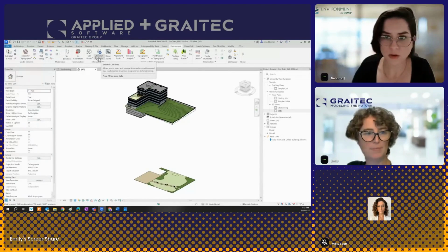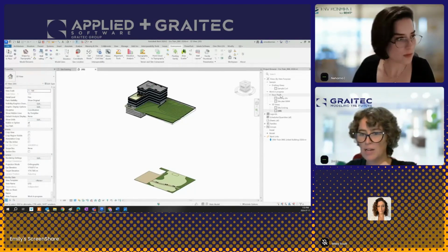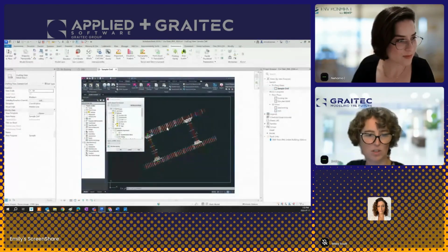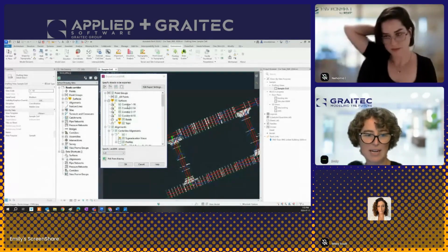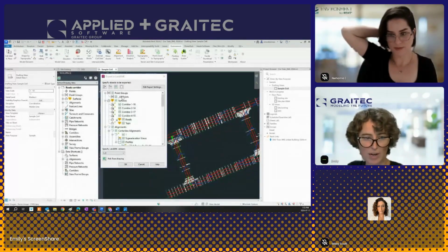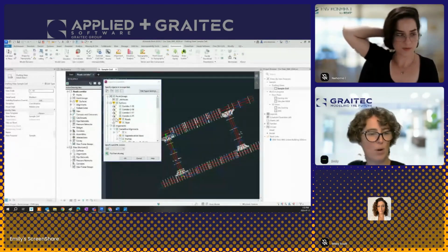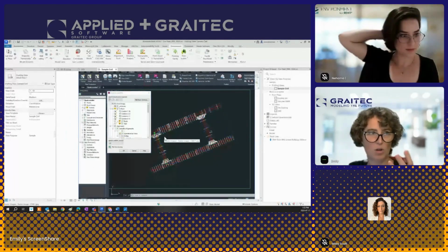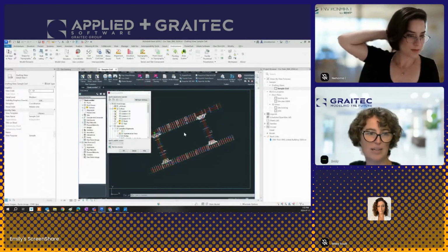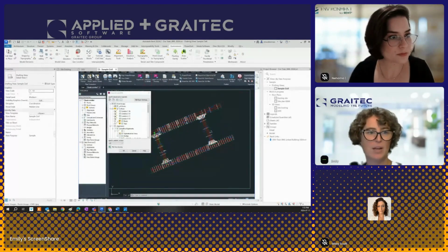So, for adding Civil 3D, in this site we've got a little bit of a sample Civil file. If we were in Civil 3D, this is what we might see, right? We've got export options here to a LandXML file. We're exporting points, corridors. If you know Civil 3D, this will make sense to you. I'm no expert. So this is a sample of what we are going to try and import into this site. This is sort of the corridor. This is what's been created in Civil 3D.